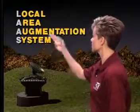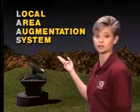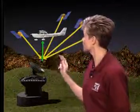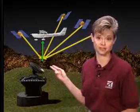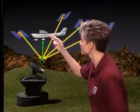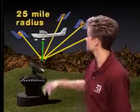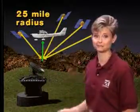For even greater precision, LAAS, or Local Area Augmentation Systems, will be used. These are very similar to WAAS. But with a LAAS, the error correction transmitters are ground-based instead of space-based, and they send the correction signals directly to the aircraft rather than relaying them through a satellite. Since LAAS correction signals will be limited to line of sight from the ground transmitter to the airplane, they will typically only cover an area within a 25-mile radius.